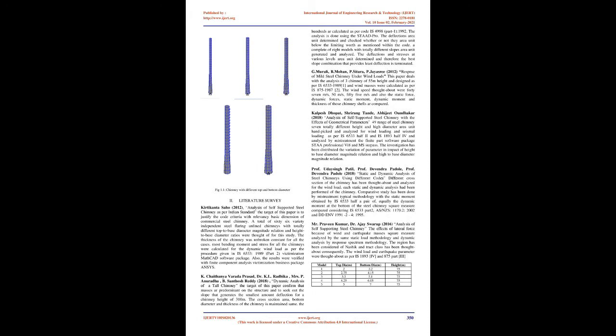With large-scale industrial developments taking place everywhere, a large number of tall chimneys would need to be built every year. Building chimneys this tall requires a better understanding of the loads acting on them and their structure. Proper design and construction of such chimneys creates self-contained structures that can withstand wind loads and other forces acting on them. Chimneys are more susceptible to wind and earthquake loads, which can cause serious problems in power plants and large industries. Numerous standards are available for the construction of self-supporting industrial steel chimneys, one of which is Indian Standard IS 6533, 1989, Part 1 and Part 2.